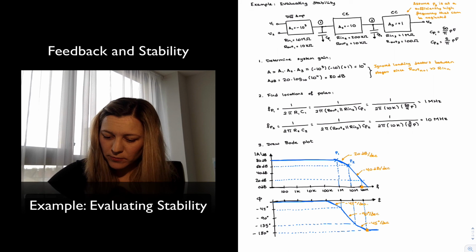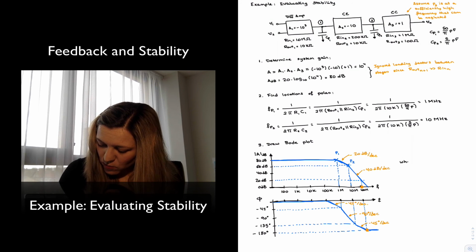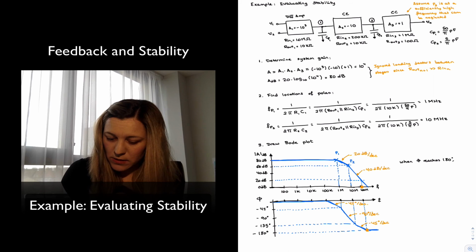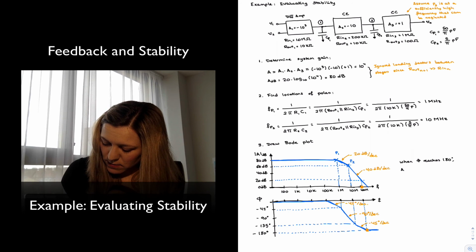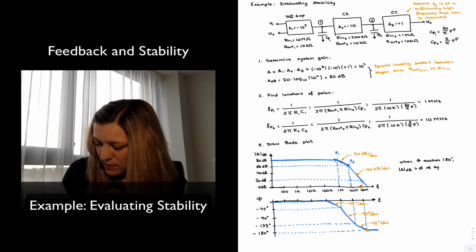Okay. Let's make a note here and say when the phase reaches 180 degrees, my magnitude of my gain in dBs is greater than 0. Therefore, system is unstable.